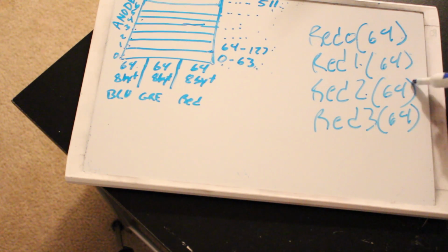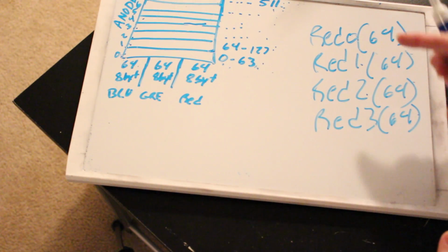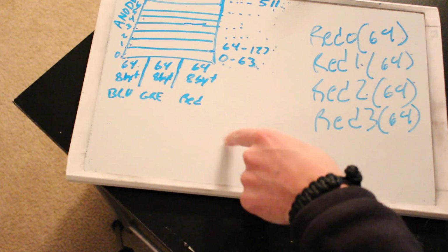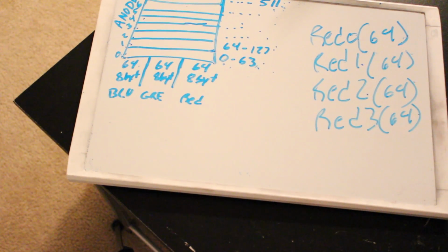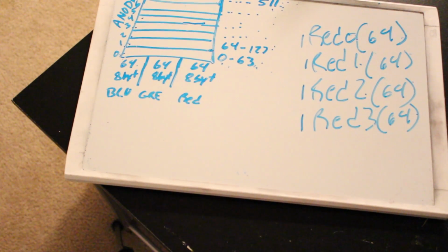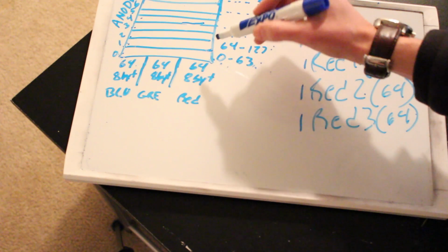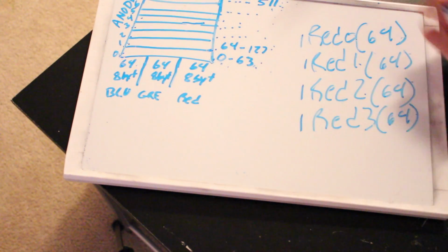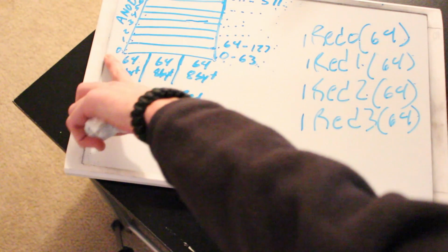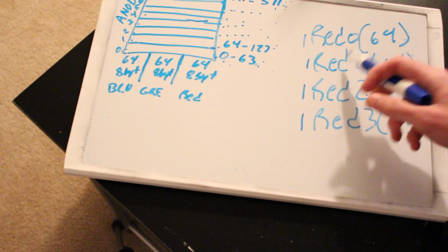Now I know it may seem a little confusing why we have 4 arrays, but that's just for the bit angle modulation. So if we were to write LED 0 here, for example, the first LED in level 0, row 0, column 0, with a value of 15, since 15 represents a 1, 1, 1, 1 on the bit angle modulation, they would all be written. So it would scan through its 8 times. So it would light this one up, this one up, this one up, this one up, all the way to the top, while making this one high.